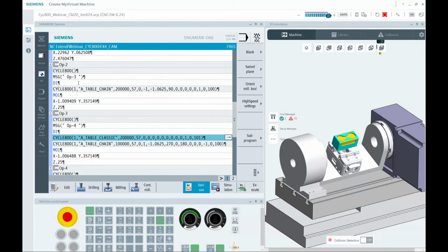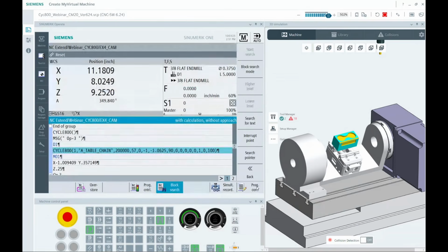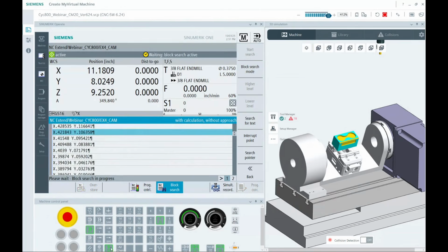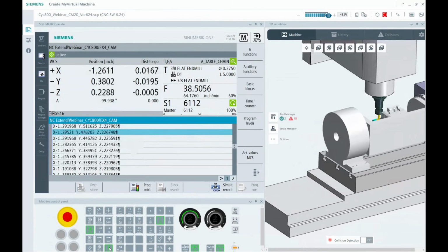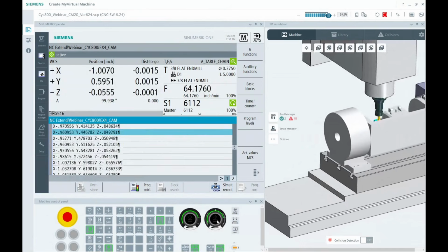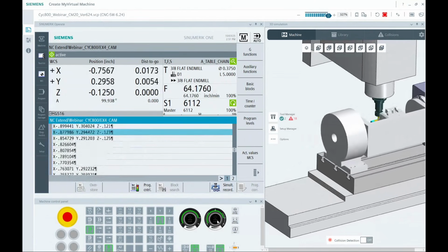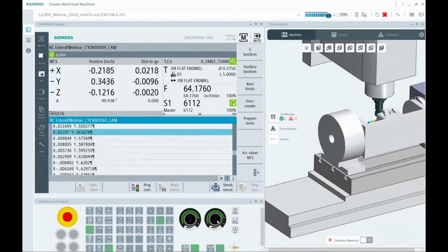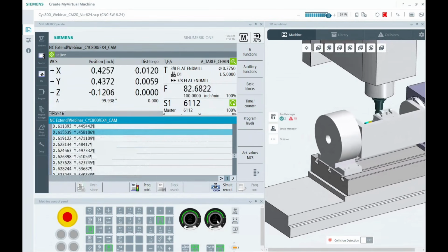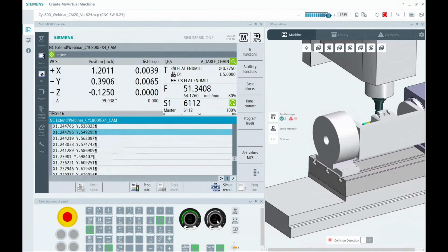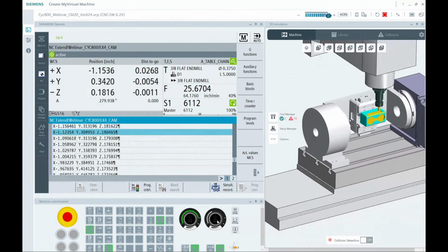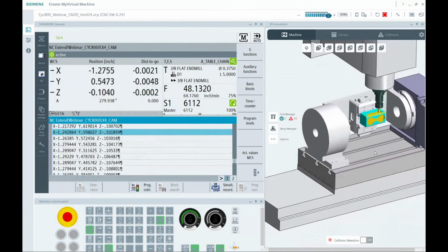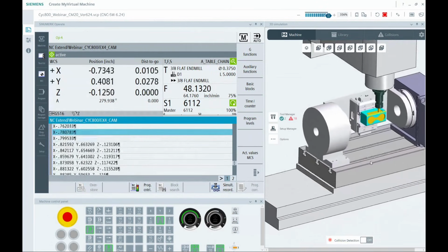So let's say, for argument's sake, now I do a quick start search from our first plane. I'm going to do a mid-program restart. All right, yep, go. So now it's coming down. Machining, we'll speed her up. Cranking around, I'll slow it down just before we do it. So here, just about there. Let's slow her down. So now you see 1, 2. Now I have full control, and I would potentially not cause a collision issue by rolling over top.